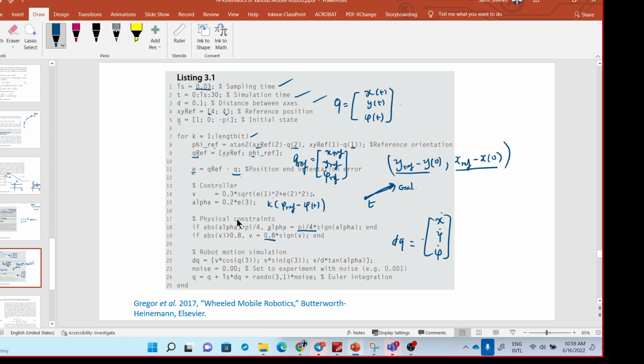Let's say the distance from the initial position to the goal is like 50 meters, and you want the settling time to be only 3 seconds, then it may not be possible, right? But anyway, the larger the value k, the shorter the settling time. So of course, first we want the settling time to be short, to be small.